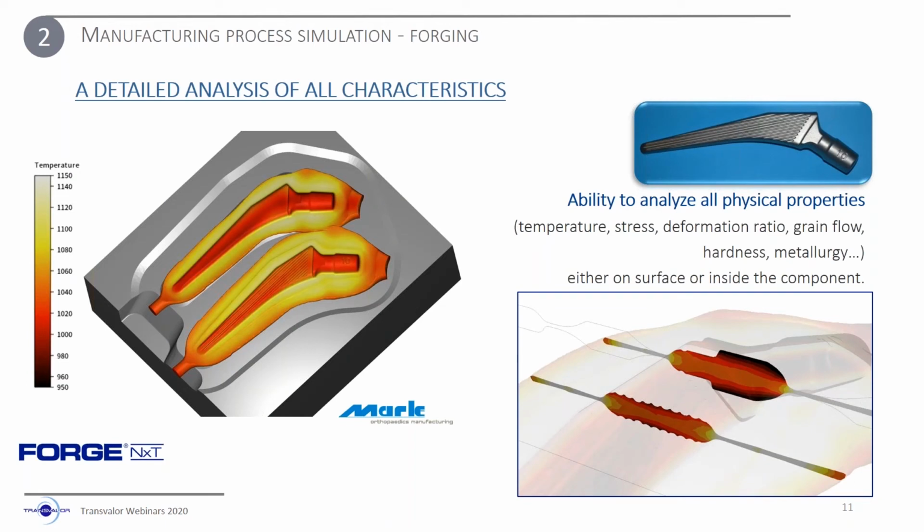At any step of the simulation, you can look at a large variety of results: temperature, stresses, deformation ratio, grain flow, hardness. You can also study metallurgical aspects such as grain size evolution or a recrystallized fraction.